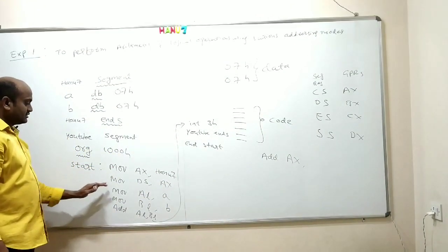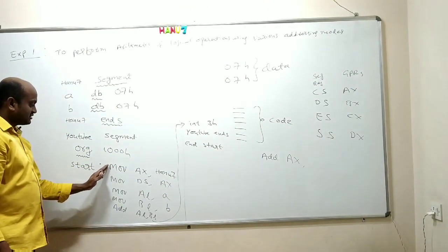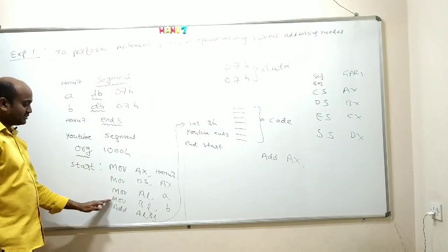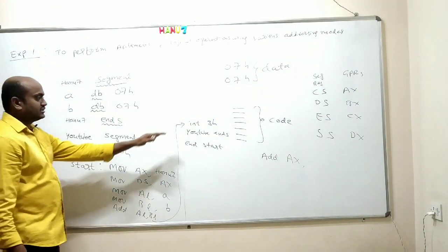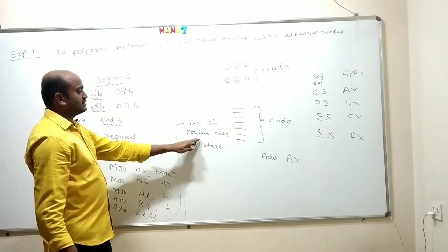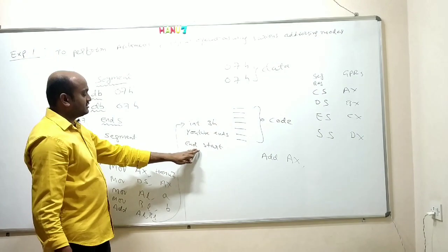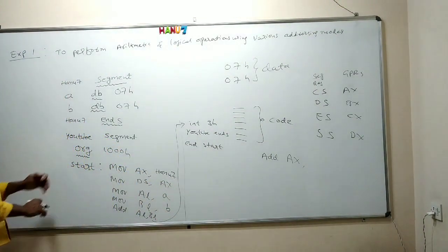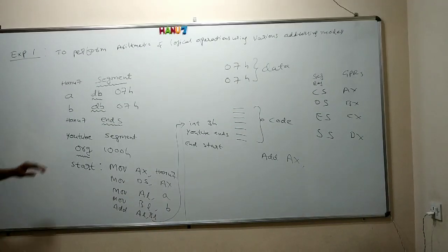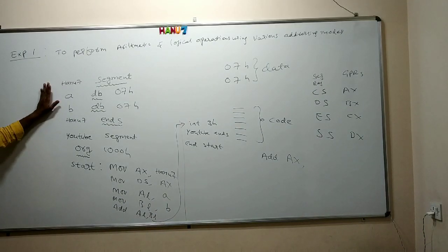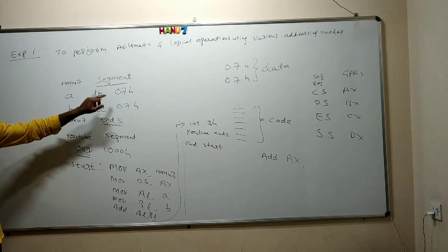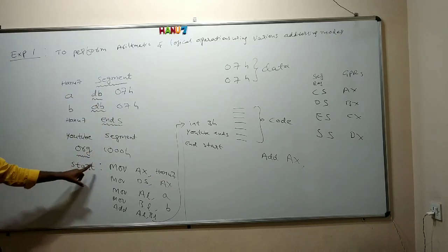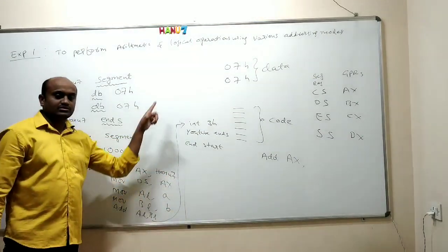So at start, we wrote first two statements called data segment initialization steps, moving the first number into AL, the second number into BL, addition, and then the breakpoint interrupt, then closing the particular code segment, and then indicating the end of the program. So this is how we will write a program to add two numbers. Two are 8-bit numbers here. This is my data, 7 and 7 is my data, and this program whatever I wrote is called code.